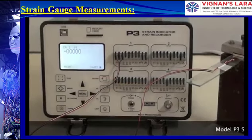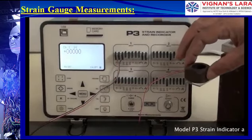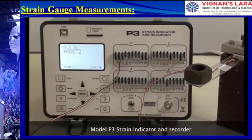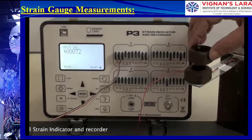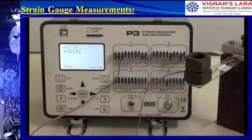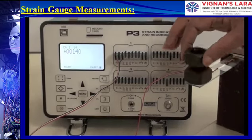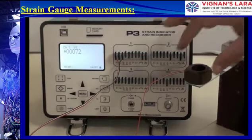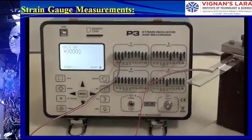The gauge is connected to a model P3 strain indicator and the beam is loaded to see if the gauge installation is satisfactory. An unchanging 0 after balancing the reading, stable and repeatable readings of strain under load, and a good return to 0 when unloaded indicates a reliable strain gauge installation.